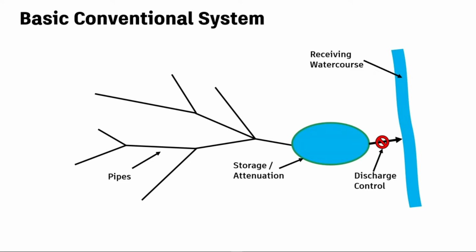These pipes will typically be connected together by manholes, which are access points along the system, allowing maintenance personnel to inspect the system, and are usually equipped with covers and ladders for safe entry. In many traditional systems, detention ponds or tanks are used to temporarily store excess stormwater during heavy rainfall events. This helps attenuate the peak flow of water into the system, preventing flooding around the system.